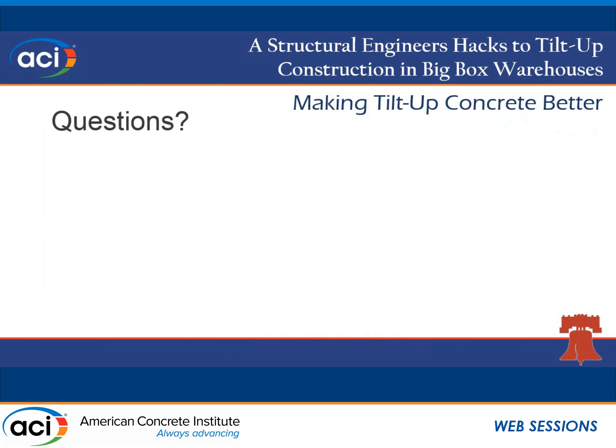Are there any questions? So we run into the same situation with dock walls all the time, and my question is, to fully pin the panel to the slab, and we have a pour back strip. How do you detail, and how are you detailing beyond that pour back to make sure that we're truly pinning the wall there and not missing out, or just engaging that pour strip and then there's not much else there?